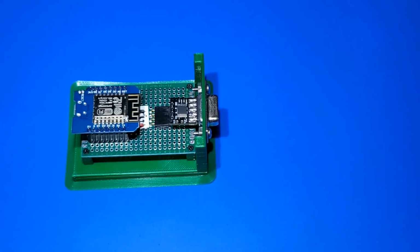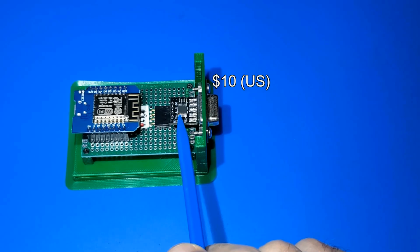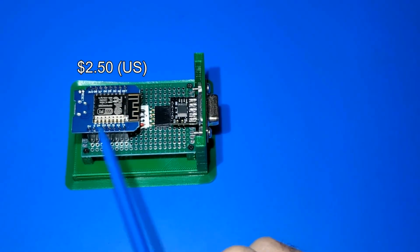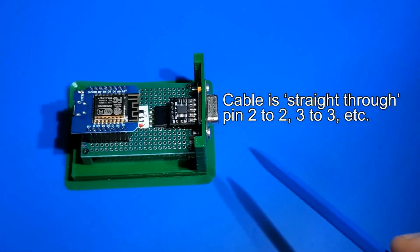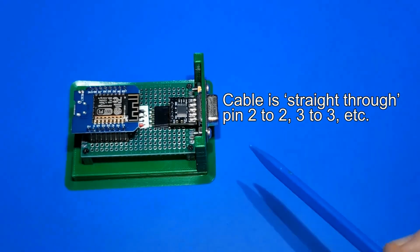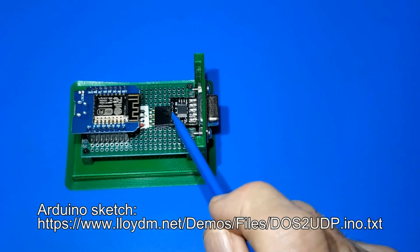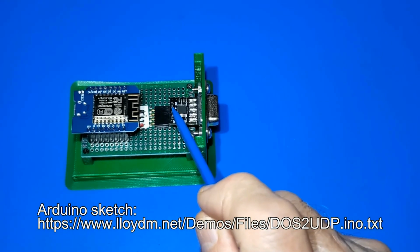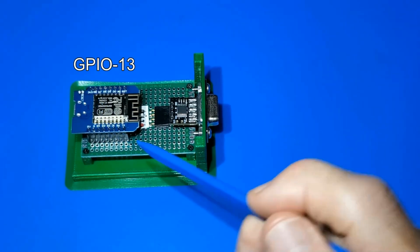This is an exceptionally simple interface circuit. There are just two components, an RS-232C to TTL adapter and an ESP12F Wi-Fi board. The adapter has a DB9 connector for serial input, and on the board there are just three wires, plus, minus, and a connection between the receive pin on the TTL end to a microcontroller input pin.